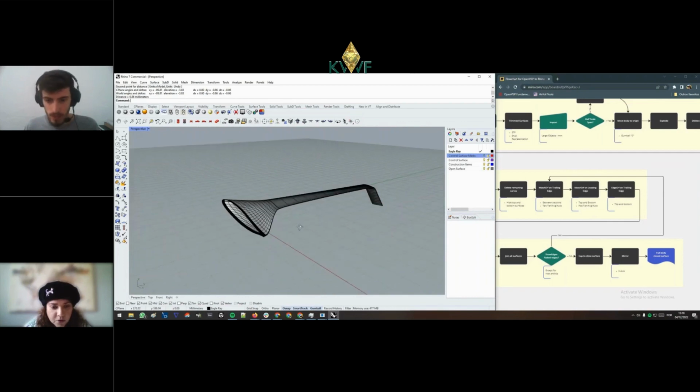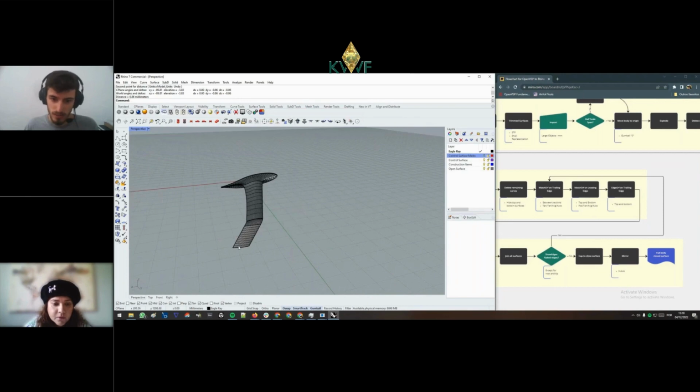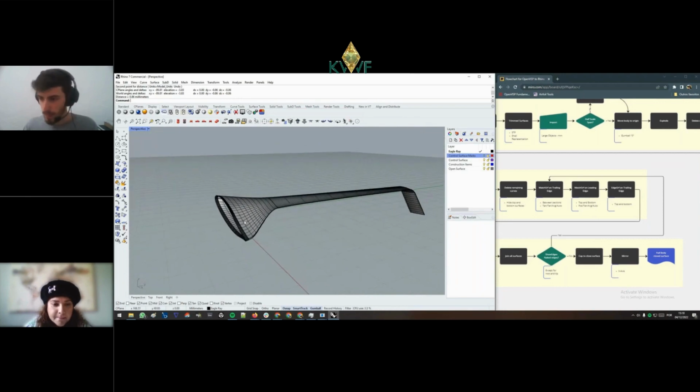Well, it really tapers off. Yeah. It's mainly because of the chord of the airfoil, because the thickness of the airfoil is dependent on the chord length, and here the chord is much smaller, and then the thickness as well.